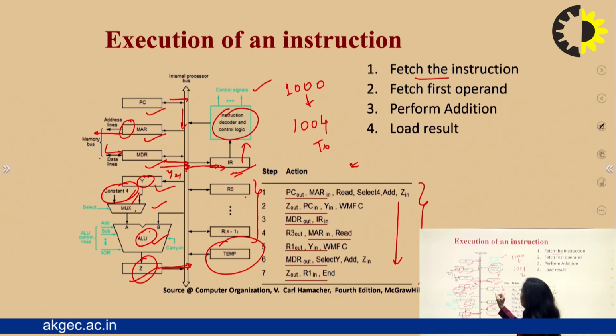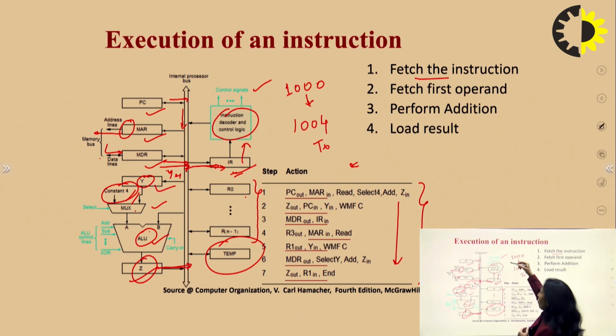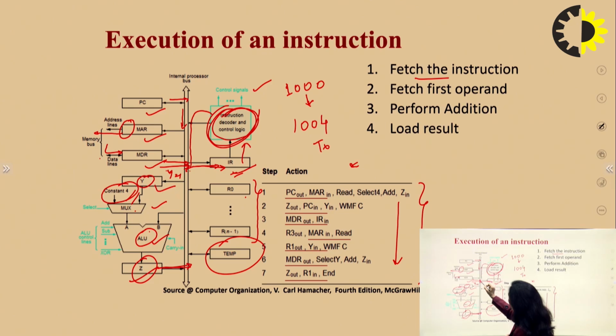This instruction register knows that it needs to fetch whatever data is inside the register R3 via the control logic. It will understand that it needs to fetch the value from R3. Again, it will follow the same path, and somewhere it will locate the value R3. From here, it will see that it's an address.